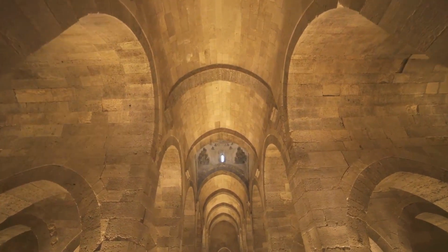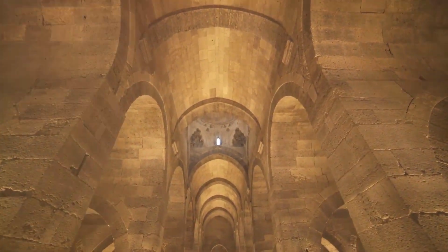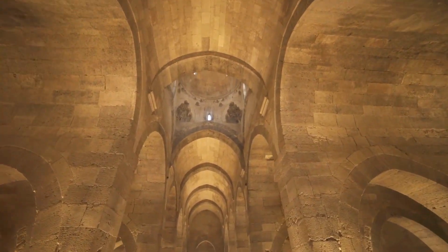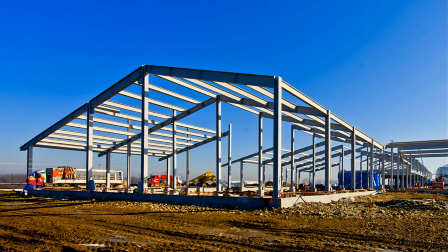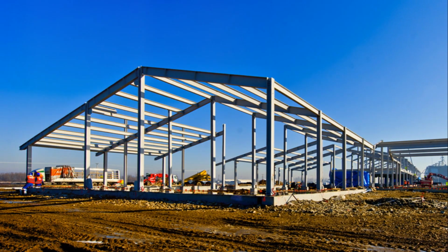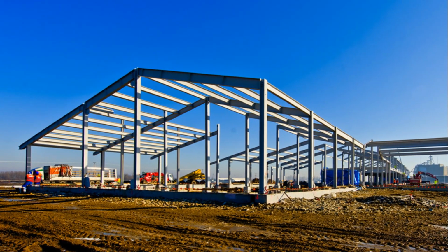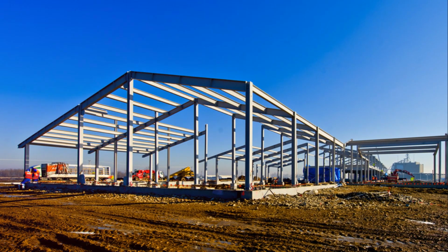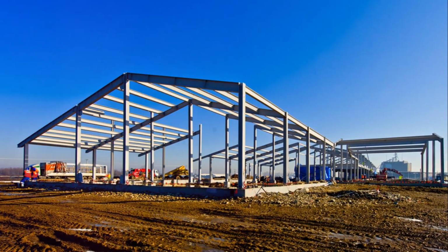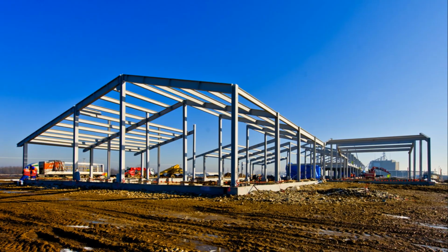Then we moved on to the art of arches, diving into the funicular shape, vertical reactions, horizontal reactions, and thrust. Remember the three-hinged arch? It's a classic example of how an arch can distribute load, with the added benefit of flexibility. Next, we focused on rigid frames, where vertical and horizontal members work together as a single structural unit.